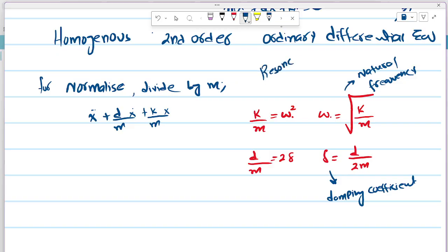You must have studied this in high school physics. So whenever the external force frequency matches the natural frequency of a body, it undergoes resonance. Whenever you're designing a mechanical system, you don't want any external force coming near the natural frequency, because when it goes into resonance, it will vibrate with very high amplitude, and it will ultimately rupture.